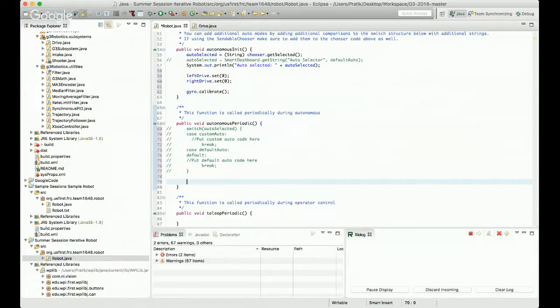So again, we're going to want to spin to the right, and we're going to assume, and this is a correct assumption by the way, that spinning to the right is an increase in the gyro angle. So if you start at 0 and turn it a quarter revolution to the right, your gyro would read approximately 90 degrees. Something of note with gyros is they do drift. The longer they're on, and the hotter they are rather, the more drift there is. So that's another reason we calibrate it right before we want to run it. So let's go ahead and do that.